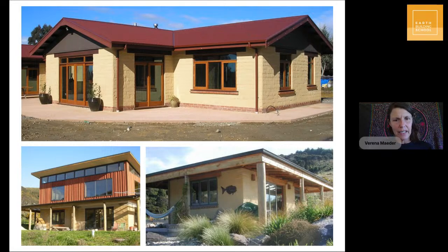I think the minimum is 600 millimeters roof overhang for earthen, solid earth walls. I would suggest you go for at least 900. It's also something you want to optimize in terms of your sun angles, shading summer sun and letting winter sun in. So I'm encouraging you to think about roof overhangs for more than one reason. One is weather protection, but the other is shading, because shading is important. Tiny houses actually overheat. So it's not just about them being warm, it's also about them not being too hot.